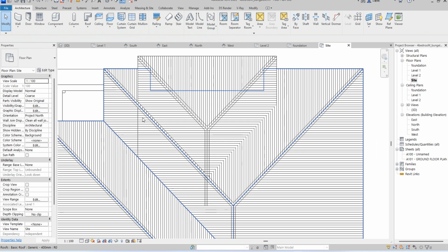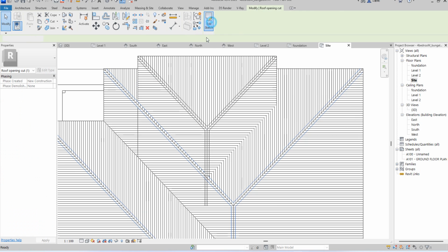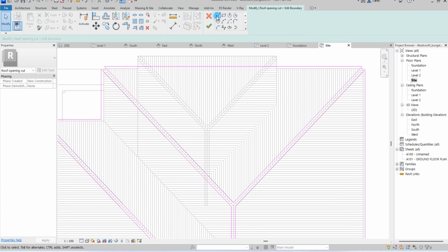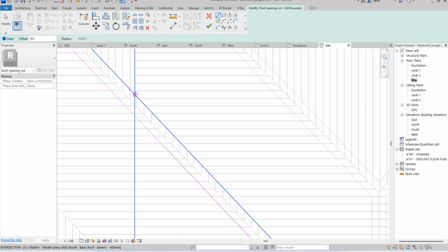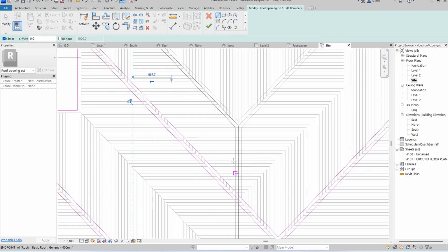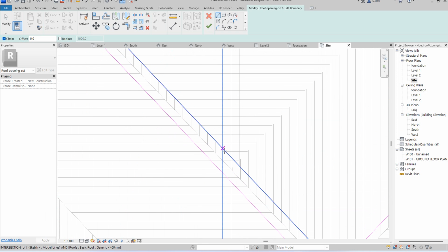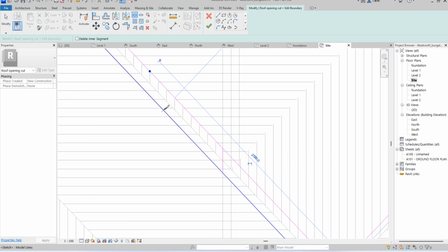So now what we do next is to cut this one off so that we maintain that plane references with the line. So before we now adjust this one to meet up the whole level. So let's go. So what we do here is that we select the opening and say edit. So edit you do here is that you cut it off from here. Okay, and you do the same thing here as well. So where it joins together, then you break this into two.